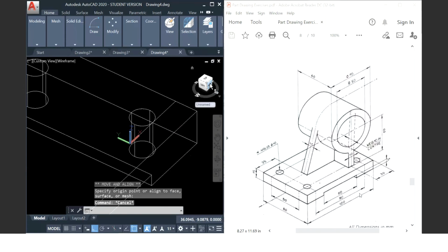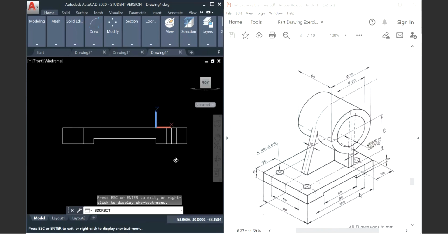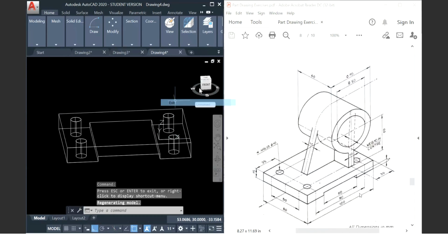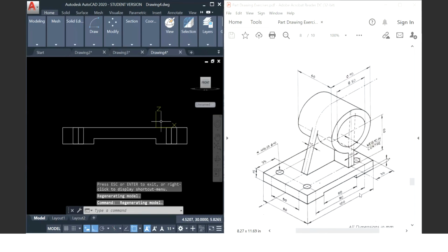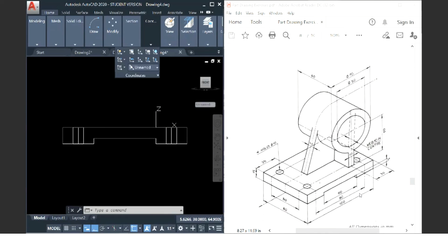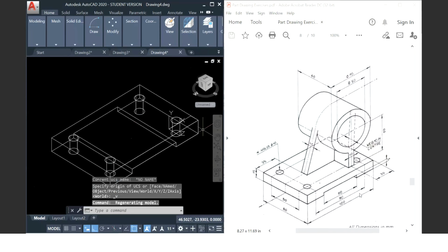So now this is the plane that I want to construct my geometric drawing on. As you can see, if I choose this plane it is an XZ plane, so I need to change it to become my XY plane. Go to coordinates, choose a view, click view. Now I change this plane to become my XY plane, right?